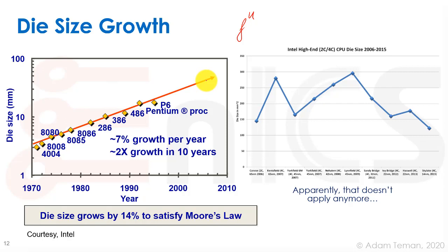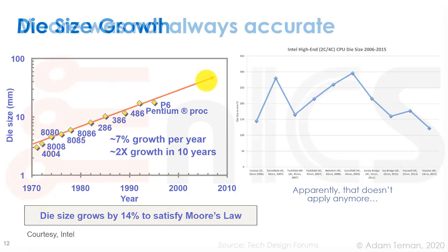There are many chips that actually continue to grow, and they're much larger than the Intel type of cores or high-end processors, such as FPGAs and different networking chips, and these are very expensive per die. We actually had Cerebras put out a wafer scale chip earlier this year, which was a whole wafer that was one chip. But most chips stay with up to a 200 millimeter or so die size, because larger than that, the yield just drops horrendously, and the price goes up such that it becomes a really high-end thing.